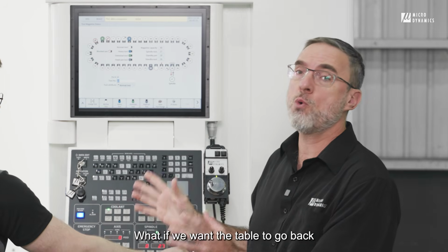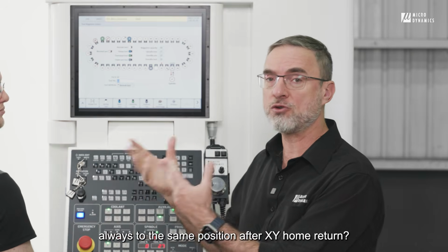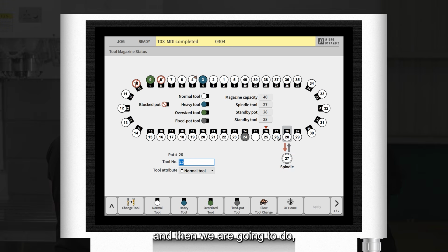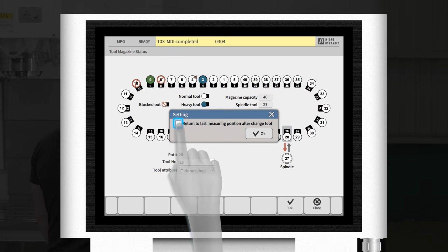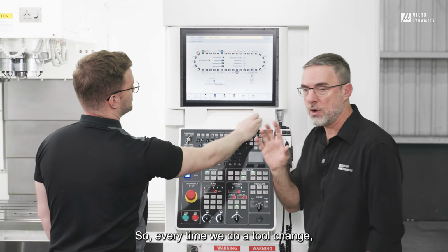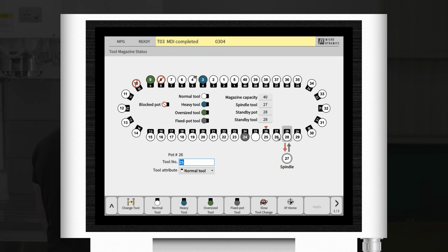What if we want the table to go back always to the same position after XY home return? Let's do it one more time. Let's put it here, and then we are going to do, okay, here in settings, return last measuring position after change tool. So every time we do a tool change, the table is going to go back to the same position.